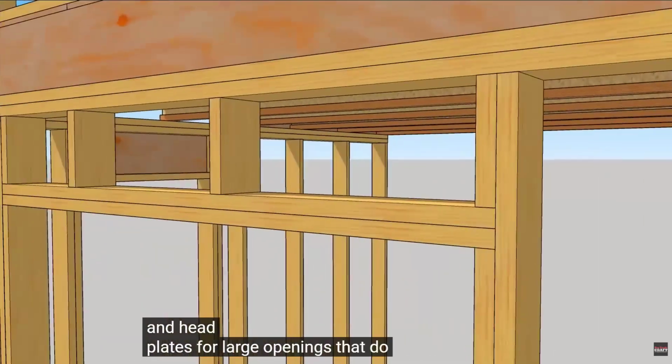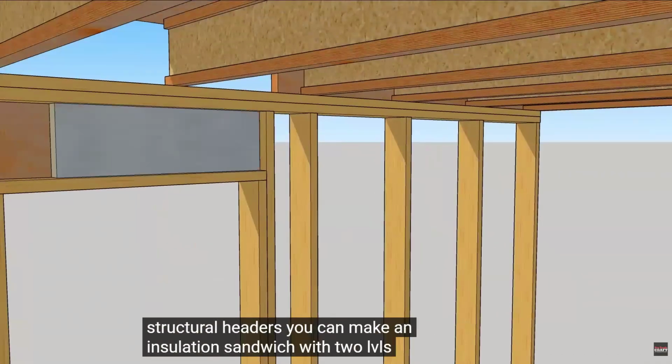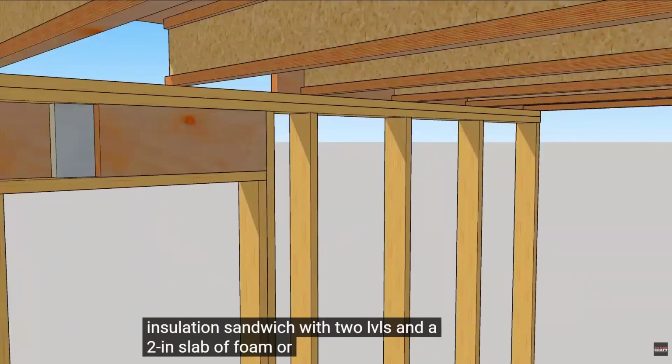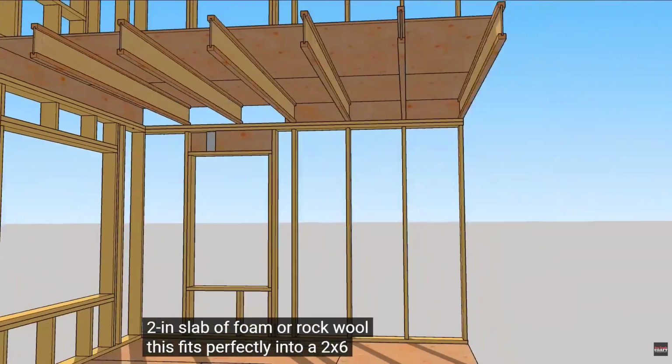For large openings that do need structural headers, you can make an insulation sandwich with 2 LVLs and a 2-inch slab of foam or rock wool. This fits perfectly into a 2x6 wall.